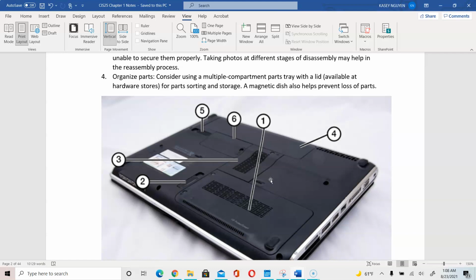A good way to also is to ground yourself. So touch something metal and make sure that you're on bare floor. When you're working with carpeted area, that can also cause static electricity. So making sure that you ground yourself before you start touching the components.